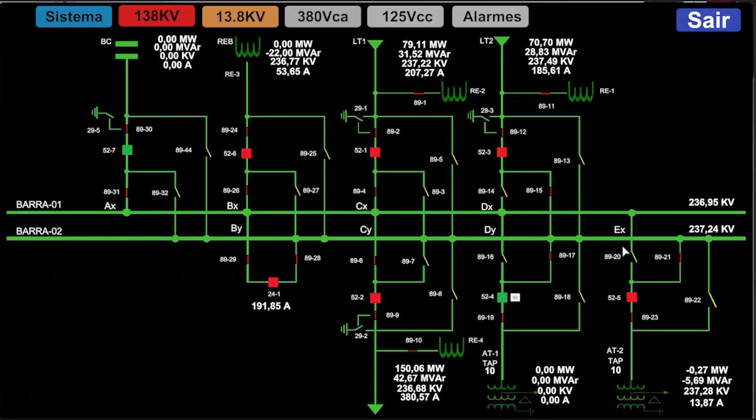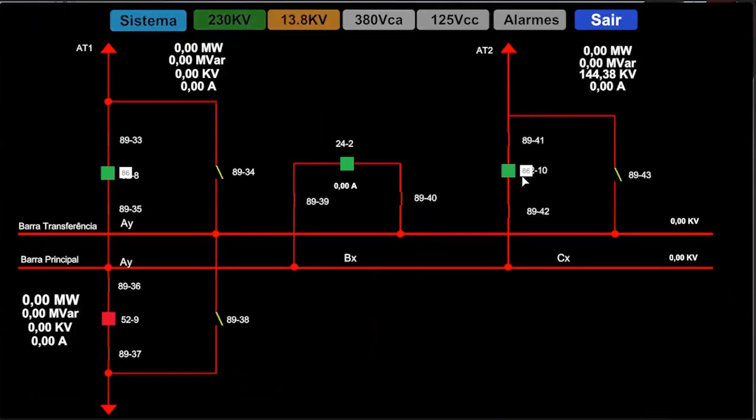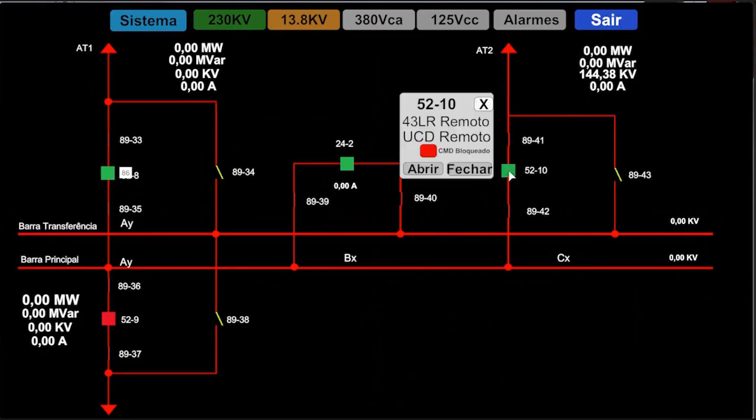Let's see if I performed the maneuver correctly. You also need to energize the low side of the transformer. You have to reset the 86. The control is locked. It is most likely because I currently do not have any auxiliary service power to be able to properly operate this equipment at this time.